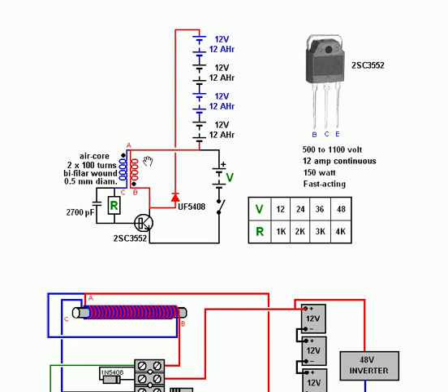When the circuit is switched on first, the battery that's powering the oscillator itself has a current that flows through this blue winding and on through a resistor into the base of the transistor, which completes the circuit, and the transistor switches on very heavily. That creates a pulse passing through this red coil. That pulse will then fail because the induced power from the blue winding will fade away in time, and the coil will then switch off.